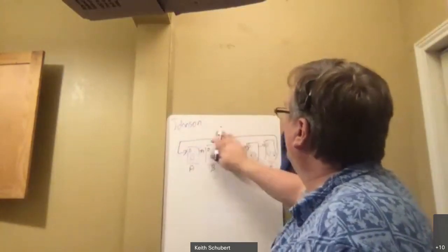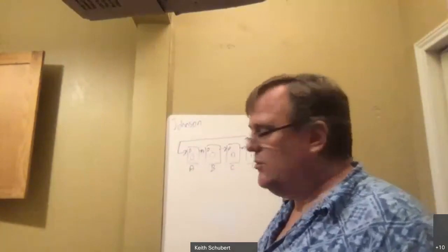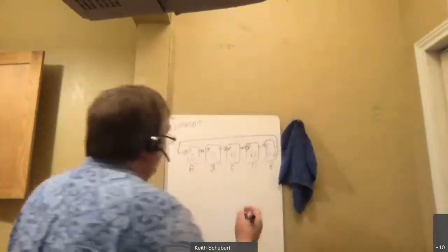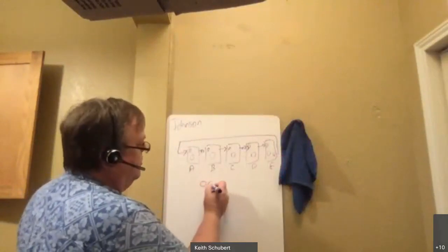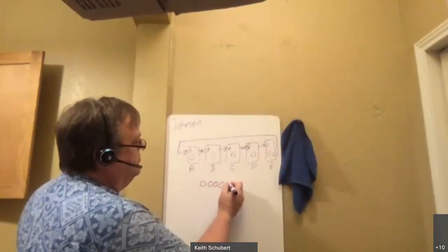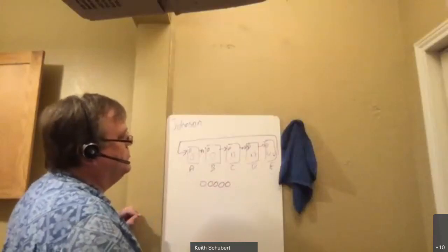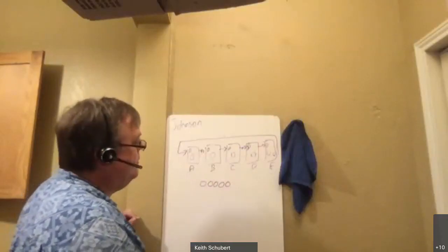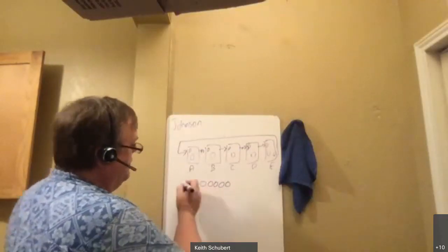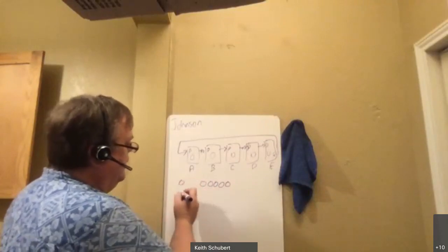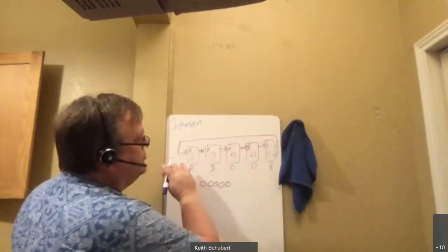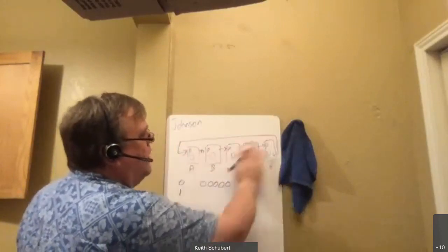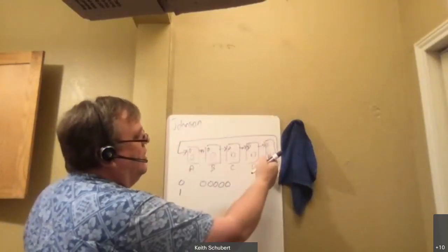Johnson counters are no longer one-hot because it's not going to just generate one-hot. So we start, our first thing of a Johnson counter is all zeros. I'll do it for 5 because that's what I've got here. So this is kind of my 0 state. When I count, I'll do a shift. So I'll do that same shift right in here.